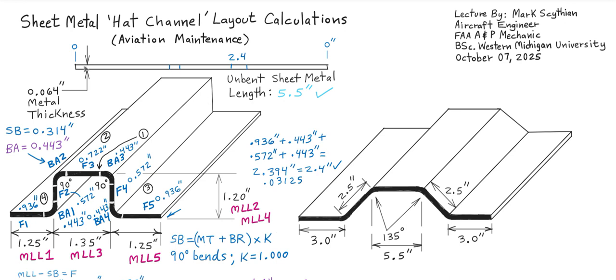You can flip it around and feed the other side of the sheet metal section into the brake, and then you bend right here. You would bend not here, but right there, because this metal will go from straight into the curve. So now you've got this really awkward, long, upside down U bracket, like that.